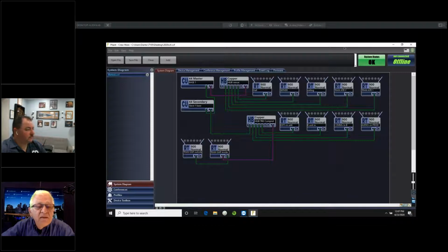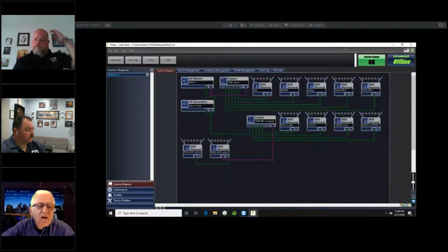In the truck compound, the antennas initially were located outside the trucks, but we found that everybody wanted to be inside the trucks. Wonder of wonders. But we didn't have enough antennas out there, so we just took the two antennas and remoted one of them over a short RG58 connector into inside the truck and put a 900 meg Sennheiser paddle on it inside. And technically, that's not the way the transceivers work. You really want to have both antennas in the space because they double send the data. But it worked pretty well in our case.